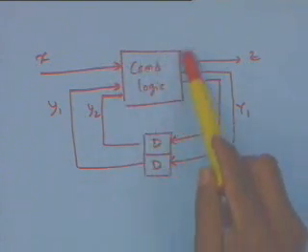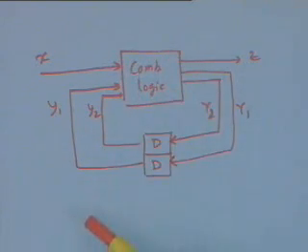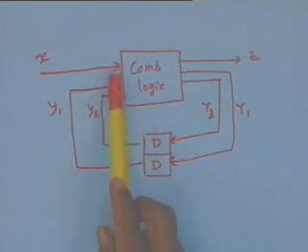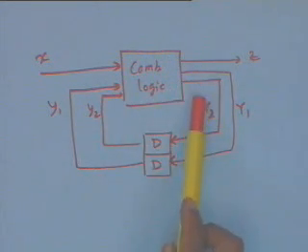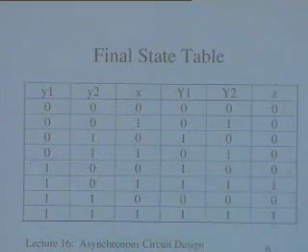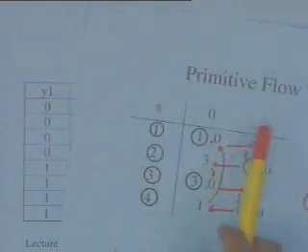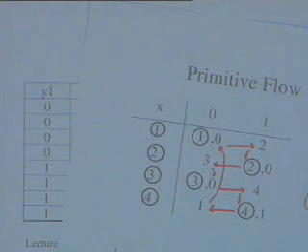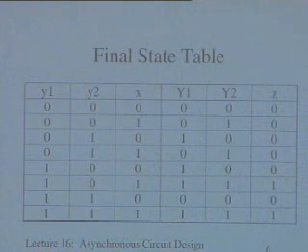So I need to arrive at a table, which I call the state table. That is the table that defines my combinational logic. It defines the 3 outputs as a function of the 3 inputs. This table is straight away the conversion of the reduced flow table. Of course here there is no reduction, there is only assignment of the outputs for the transient states. So now I have this.